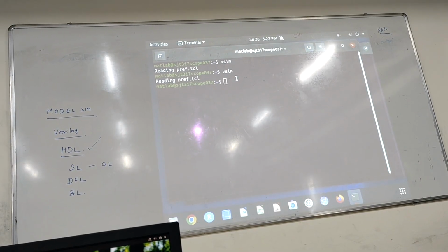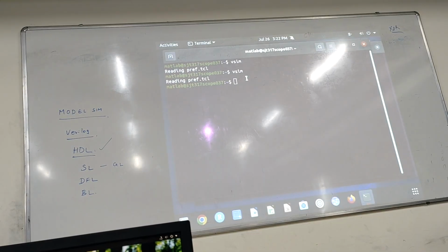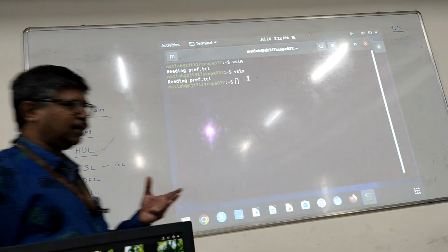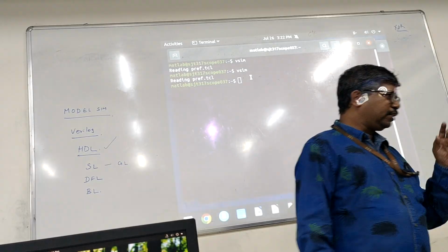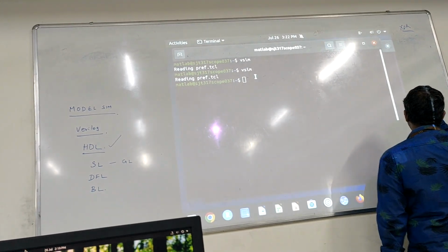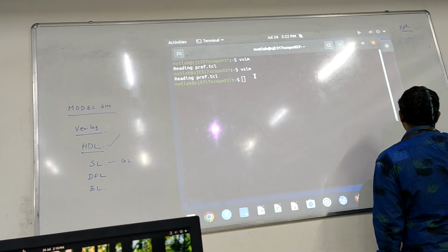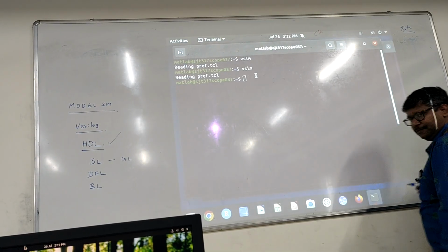To define a system or a logical circuit, we can use a truth table. If you provide a truth table, you can easily understand the functionality of that particular circuit. Let us take a half adder. The truth table will have A and B as inputs, and the outputs sum and carry.